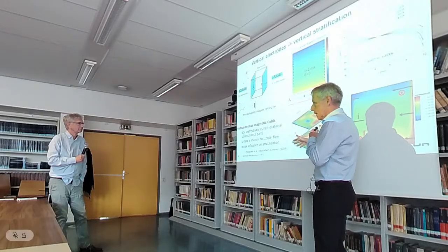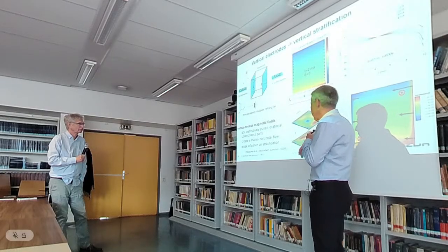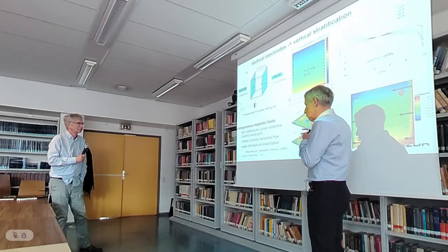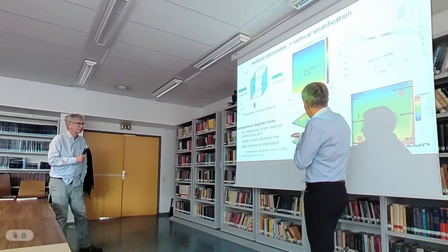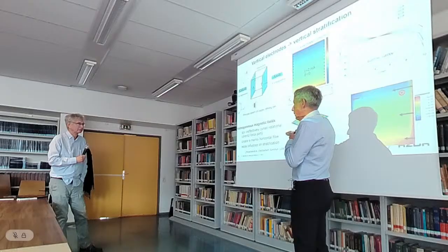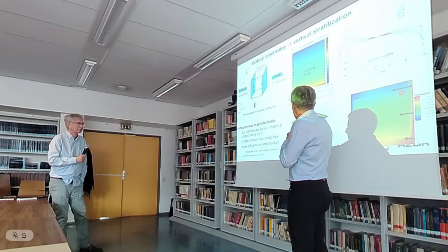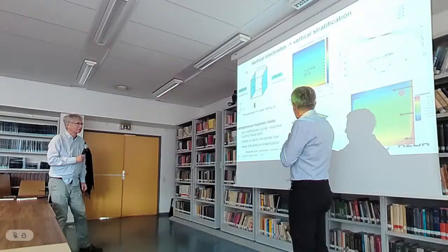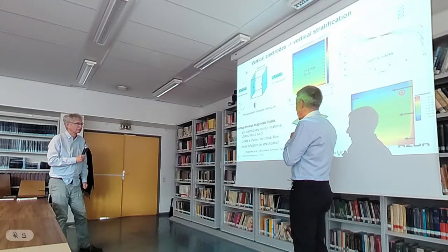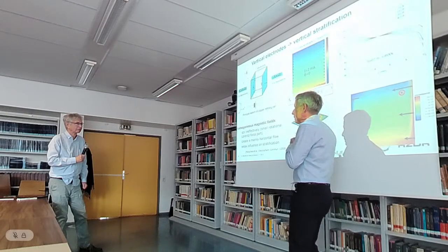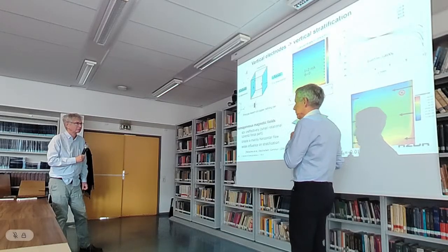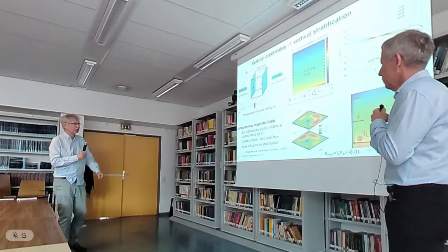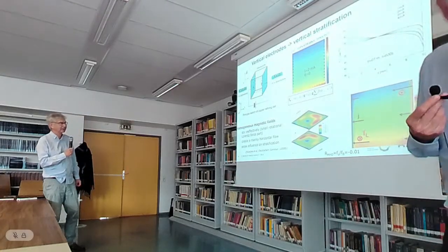But the modified magnetic field that I show on the next slide works much better because it actually stirs in the vertical direction. In case you do a homogeneous horizontal magnetic field, it tries to accelerate the electrolyte at both sides of the electrode in the same direction, which doesn't give you a circulation, basically. Maybe we should see the next slide to see how it's quantified.